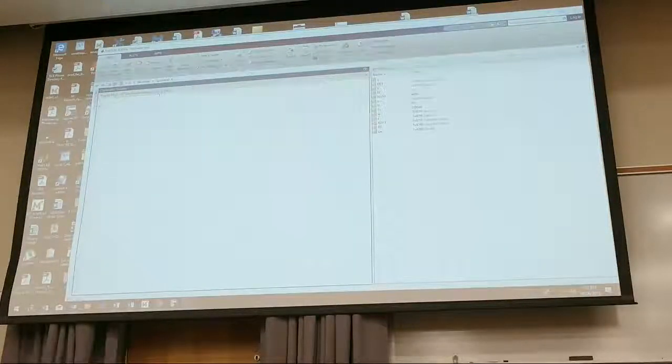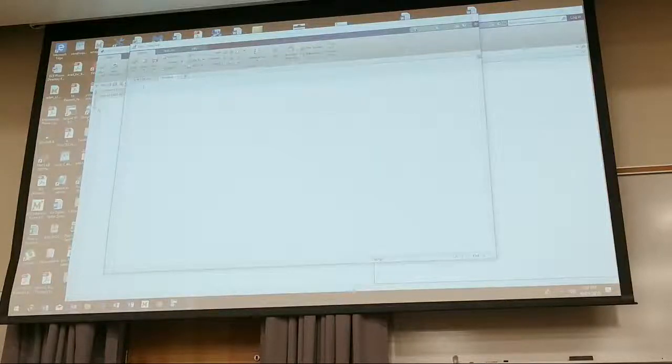Here, this is called a workspace. I don't ever write code in here. All the code I write is in what's called an M file. If you want to do that, you see how it has new script up here? You just punch new script. Every time I create a new script, I type CLC right off the bat. That makes sure the workspace goes clean. After that, usually I put close all, and then clear all. That means nothing's in memory. I get rid of anything in memory, because you can have something in memory you don't realize is going to be used over and over again. I'm just telling you that.